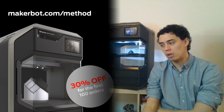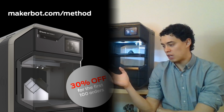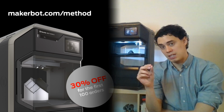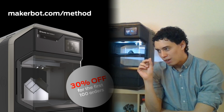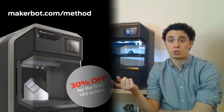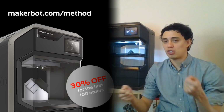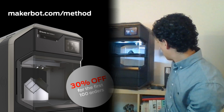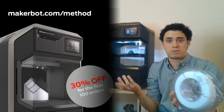So overall, taking it back to the beginning, why would you choose a resin printer versus an FDM printer, or an FDM printer versus a resin printer? If you're printing something very intricate, something like jewelry, very nuanced objects, probably you could use a resin printer. The thing to keep in mind, though, is that the resin process itself can be really tricky, right? It's hard to manage, keeping the resin in place. It's not as easy as just keeping a spool of filament around, which is kind of static, right?